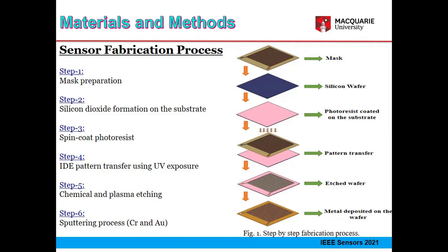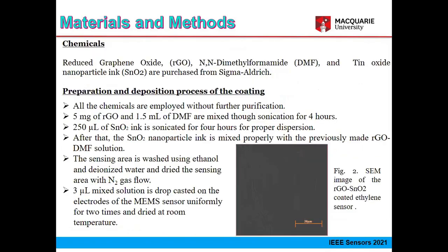After that, a sputtering technique is applied to deposit 20 nanometer of chromium first and then 500 nanometer of gold on the substrate, acting as a guard plane. The IDE pattern is 15/50. This implies 5 sensing electrodes for 1 excitation electrode, and the gap between the electrodes is 50 micrometer.